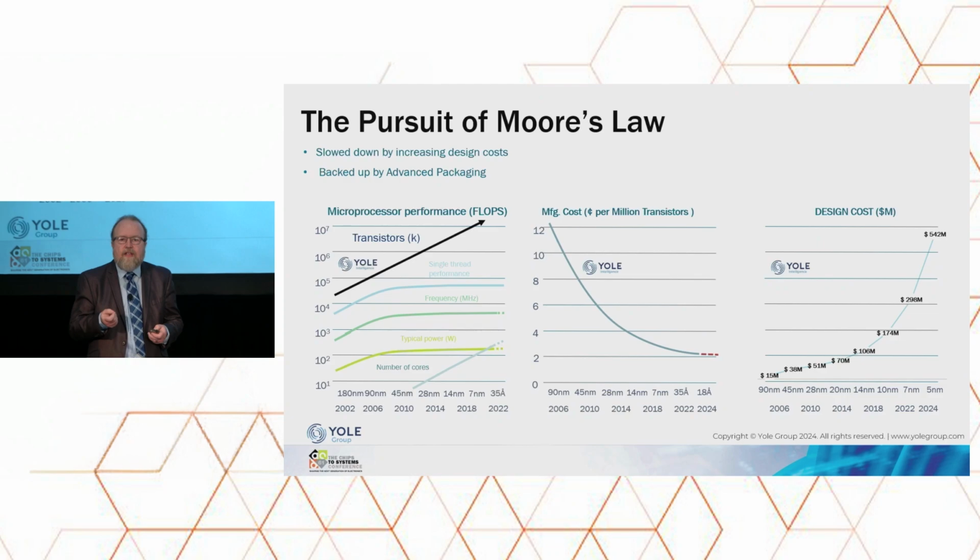Eventually, if the size of the system with multiple transistors and multiple cores gets too large, we're going to be reaching the limitations of being able to manufacture, because the chip size is too big for the reticle. And that's going to be a huge impact. If you can't make your system on chip, your large heterogeneous solution, small enough to be able to manufacture, then you're not going to market.